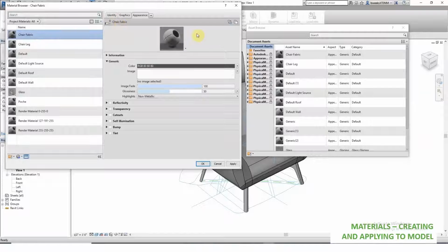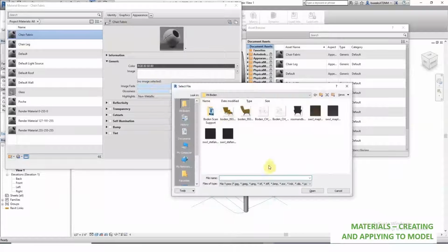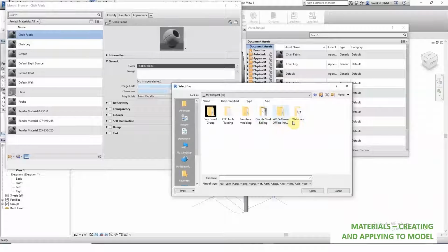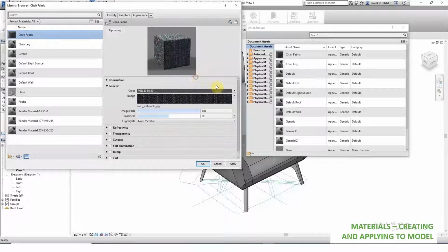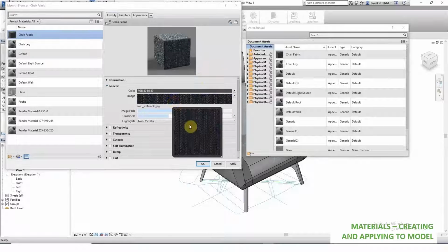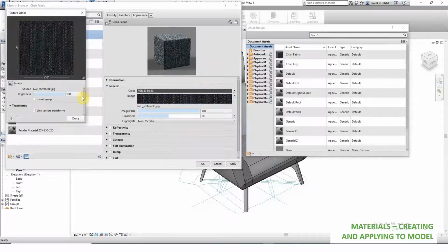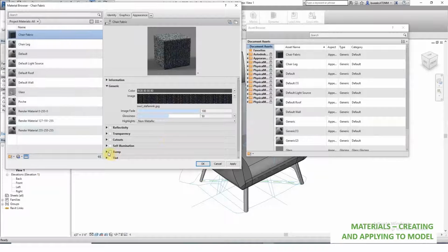And again, to do that, I clicked on the box with the arrows symbol to the top right at the appearance there. So now I'm going to start adding my material image to the project material I created for chair fabric. So there it is. I like to see it depending on what kind of surface it's going to be on to make sure it looks right. Right now the image is showing up as a 1 foot by 1 foot image. Well, that's just going to be a swatch of fabric. So I'm going to change that to be a little bit more realistic, maybe a 6-inch.